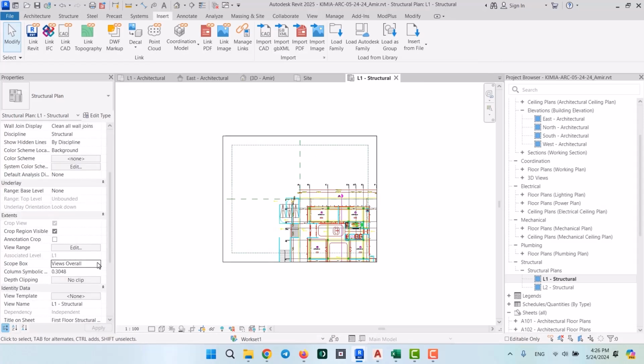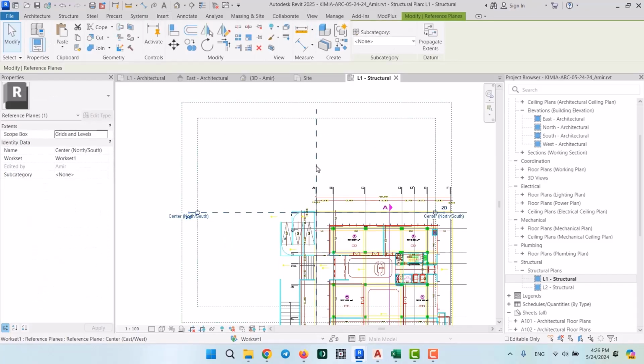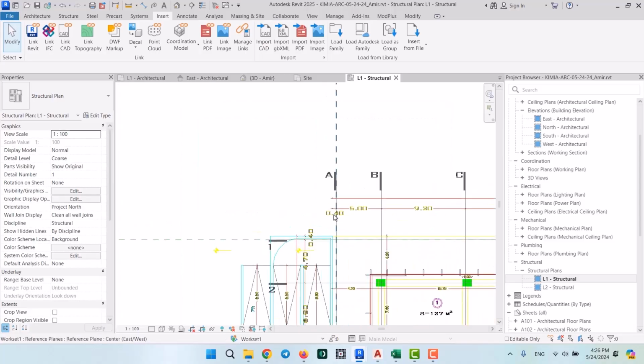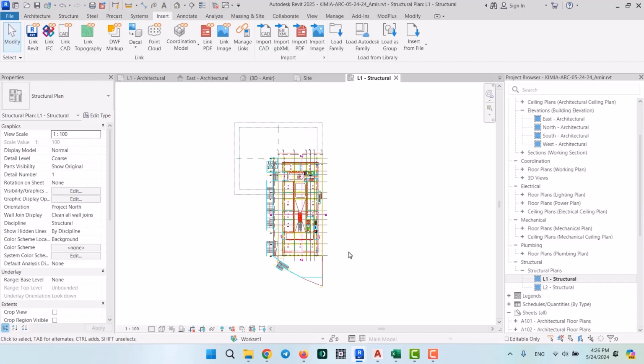Now you see in Revit's newest version, the intersection of these two reference planes that you see over here actually makes for the 0 point of your project. Do you see the reference planes here? You can see that the intersection of them is right on the intersection of the grids that we chose. Alright, now I have imported my CAD plan.